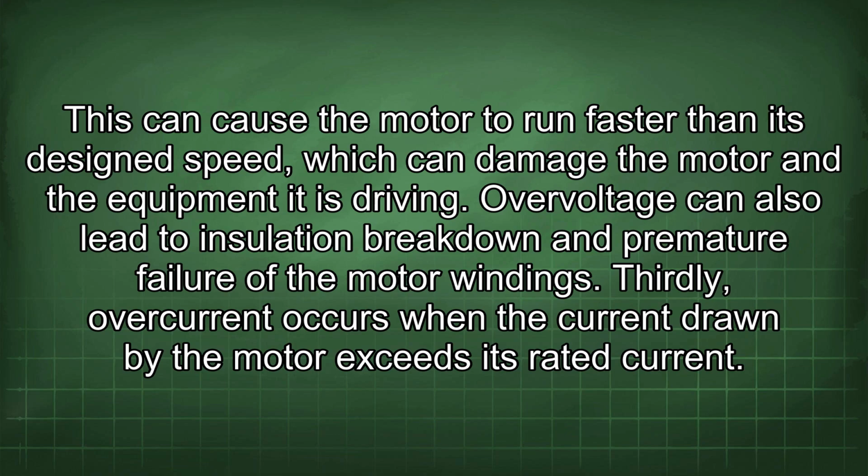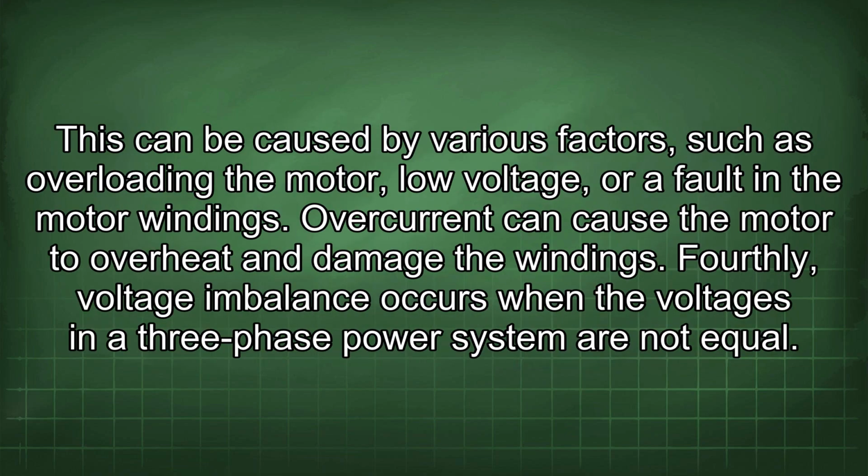Thirdly, overcurrent occurs when the current drawn by the motor exceeds its rated current. This can be caused by various factors, such as overloading the motor, low voltage, or a fault in the motor windings.